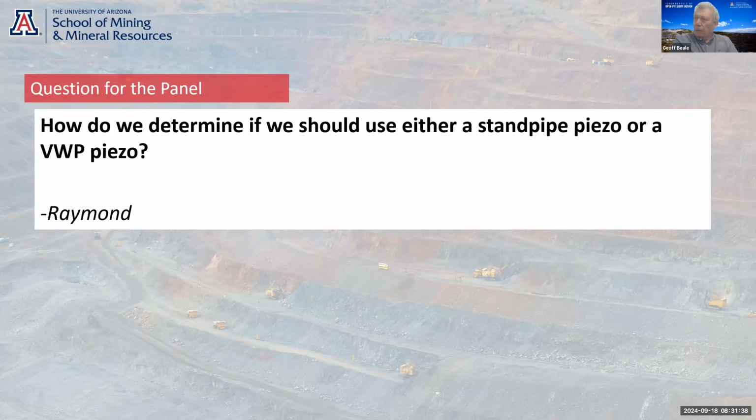The other thing, as you'll get from the course, the other thing to think about is, I always say get as many water levels for a site as you can. And whenever I go to a new site, I never look at the permeability data. The first thing I look at is the water levels. And if the water levels are all similar, I know the system's connected. If the water levels are all different, I know you've got discontinuous flow.